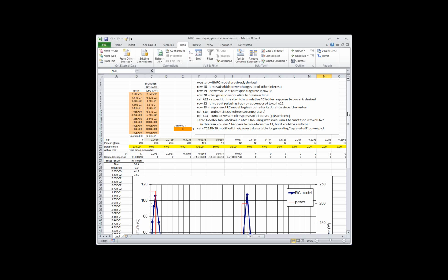That means you need to solve the roots of a polynomial, which you can't do with simple features in Excel. I've tried. One of these days I'll write myself a Visual Basic program to do a root finder. You can probably buy a third party one, but to me that kind of defeats the purpose of using Excel if you can't just use the built-in features. But anyway, that's the problem. A Cauer network requires that you factor the roots of an nth order polynomial.